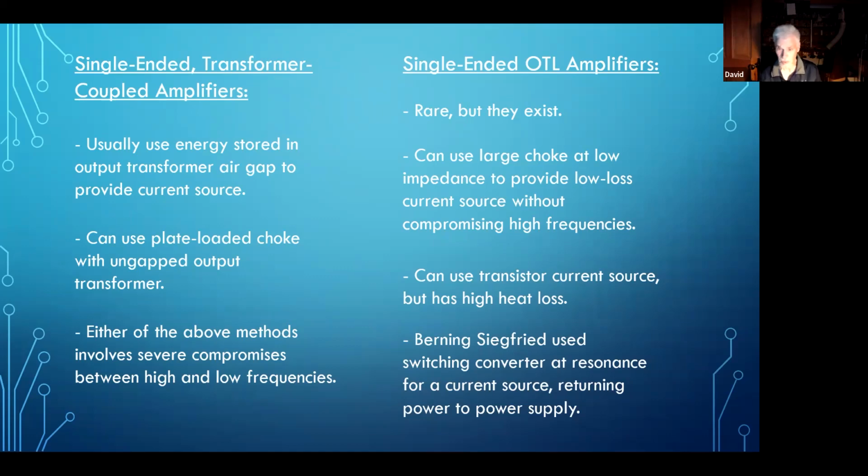It may introduce some other things that are a little less pure, like more power supply modulation because it's more like a class AB amplifier. But it really is, in a sense, a single-ended amplifier in that a single output tube is controlling the output waveform for the entire cycle. It's not being crossed over to another tube.